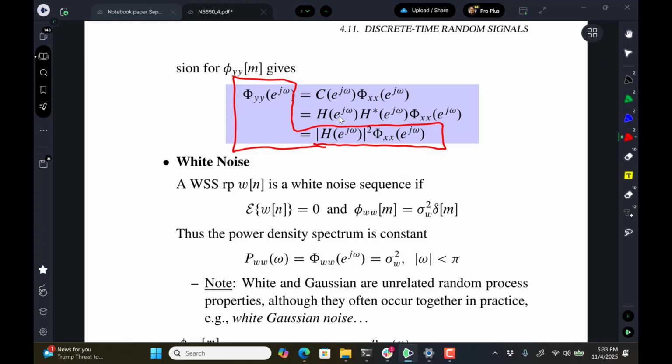I haven't mentioned, although I should have, that the power spectral density is a non-negative quantity. So if you have a signal generator producing some waveform and you want to estimate its power spectral density, it's delivering that power spectral density, say, to a 50 ohm load. I'm thinking of going into the lab now where you have a generator that has a 50 ohm source impedance, and then you're going to drive it into a spectrum analyzer that has a 50 ohm load impedance built into it. And the waveform you see on the spectrum analyzer is its power spectral density.